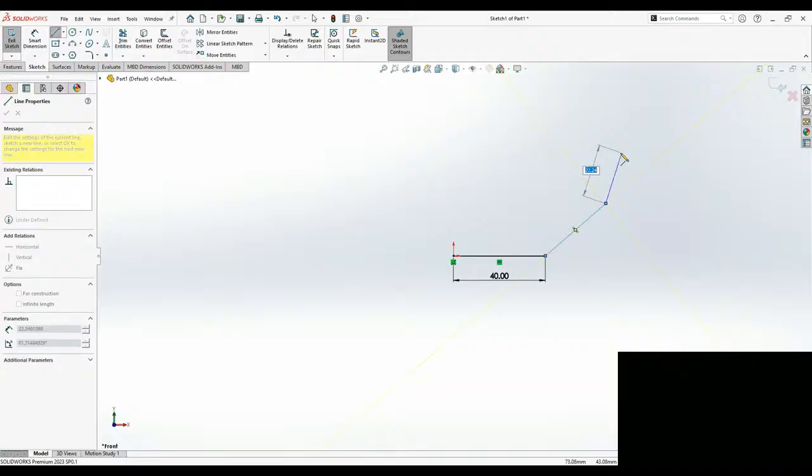Now I'll simply do the sketch so that I could even show you how you can customize your sketches if you make mistakes. Now what I'll do is I would like to have the perpendicular, but I would like to keep it slightly deviated from the perpendicular relation so that I can make it perpendicular later by just adjusting the geometrical constraints. Yeah. Now let me simply draw a sketch like this. Yeah. And then I would like to have the horizontal sketch, but I would like to not consider it now. What I'll do is I'll simply extend it like this, and I'll simply close the sketch.